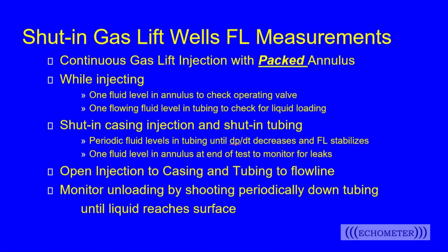Okay, that's fine. But let's look at about 10 more slides here on just shooting static liquid levels on gas wells. And right now we're going to talk about a gas lift well where we have a packer in the well, where we have a sealed annulus, a packed annulus. In essence, the flow up the tubing will act just like a flowing gas well, but we're just injecting gas into the well to help unload the well.